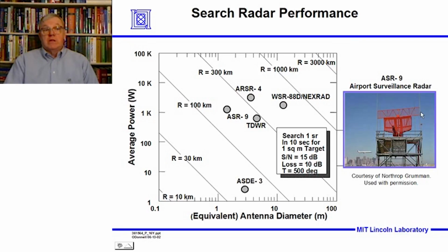These radars also, you can see another antenna above here, and that's for the beacon tracking. The radar is a non-cooperative sensor, you understand, and whether the target wants to be detected or not, if it has a reasonable cross-section, you can illuminate it, get a backscatter, and detect it. With this beacon system, which operates in tandem, in parallel with the skin tracking radar, so-called, a signal is sent out at L-band, 23 centimeters, to the aircraft, where the aircraft have a receiver transponder on it, which listens constantly, and when it receives a message, it's literally a coded message saying, "Hey, I'm a beacon system, tell me where you are, and who you are, and what your altitude is."